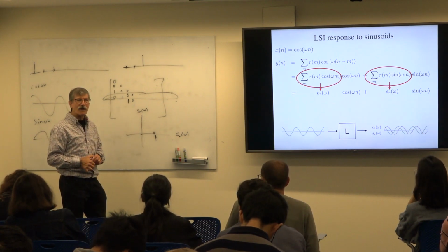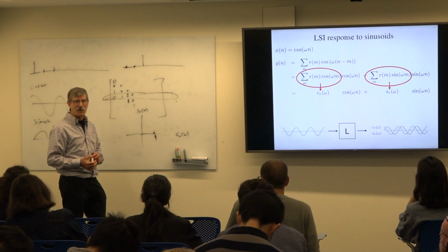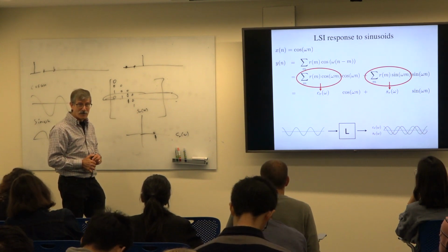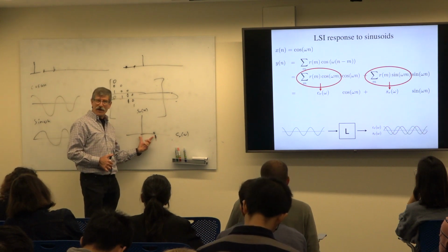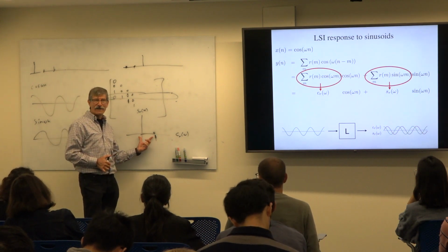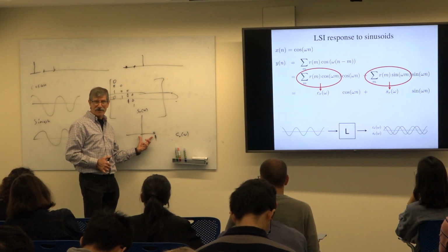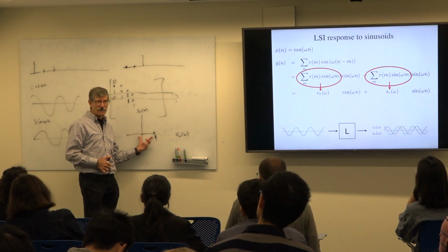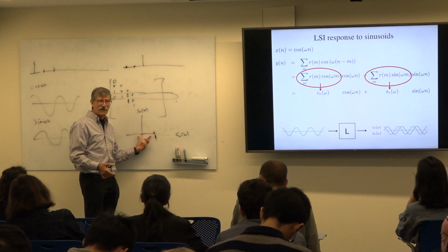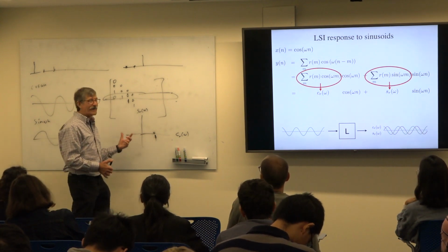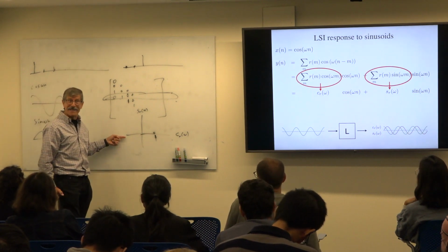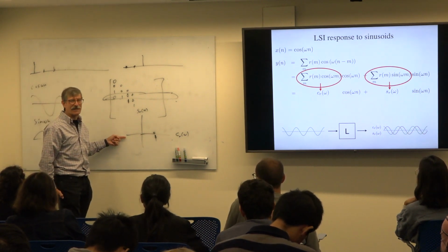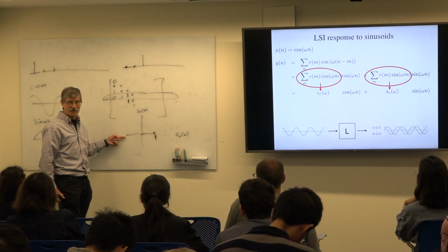Which means that if I put in a cosine wave of any frequency whatsoever into this system, I am going to give it an amplification of 1, meaning I'm not going to amplify it, and I'm going to give it a phase shift, the angle, of 0. Otherwise known as, when I put in cosine waves, they don't change. I already told you this is the identity, so now it's in the frequency domain. It's the identity. It doesn't mess with your signal. Okay?